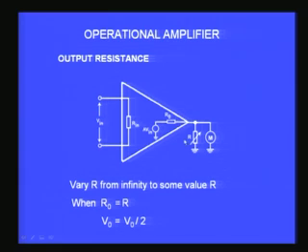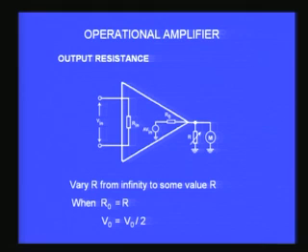Here you should also remember, I should caution this, I have assumed this voltmeter which measures the output voltage has got infinite resistance or very large resistance compared to the resistances that I have in the circuit. In this case, the output resistance in general will be a very small value.